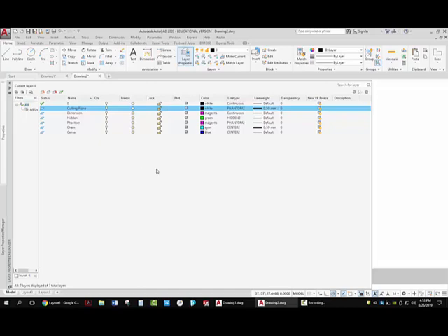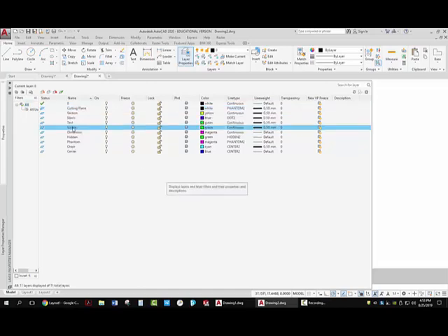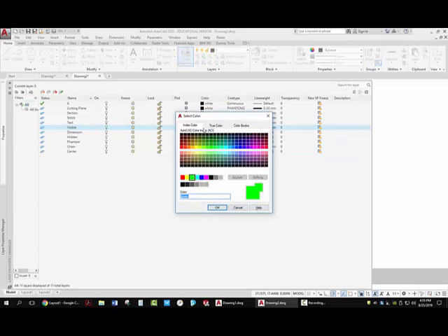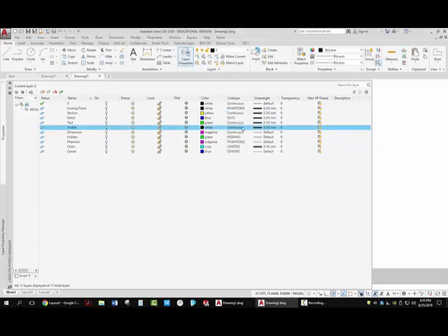I'm going to pause again. And I'm back. I just created the visible layer for visible lines. I wanted to point out something here as well. It indicated in the handout that the visible line should be white, and you might be looking for white here and not see it, but through this little quirk in AutoCAD, black is actually identified as white. I can explain that at another time, really based on something that's a legacy. Otherwise, visible lines are going to be continuous. So we have two different line weights, 0.25, which is the default, which is half the line weight of 0.5, which is what we have for the thicker lines.